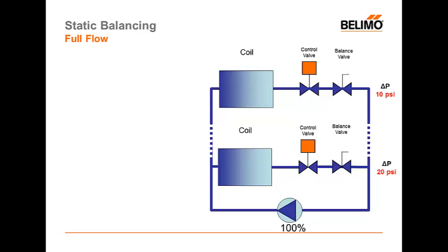This means that the water flows out of the pump and directly into that first branch run. It goes through there, and that first branch run is closest to the pump on the return, and therefore the return water is at its lowest pressure point there. So I have high pressure water coming into the first zone and low pressure water coming out of the first zone, and therefore I have a very high differential.